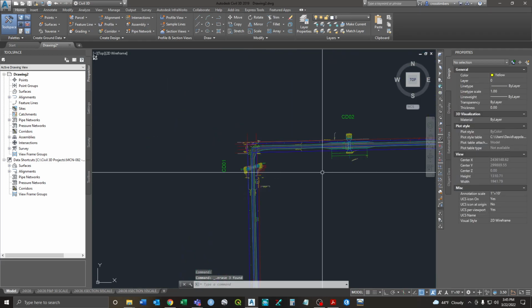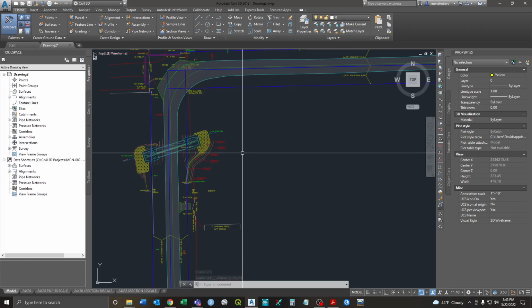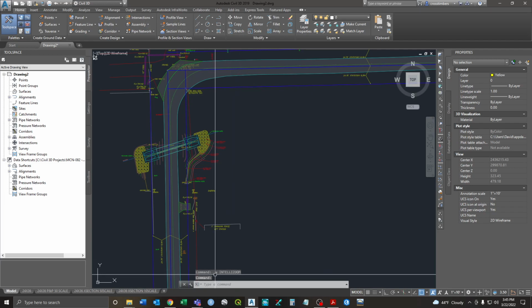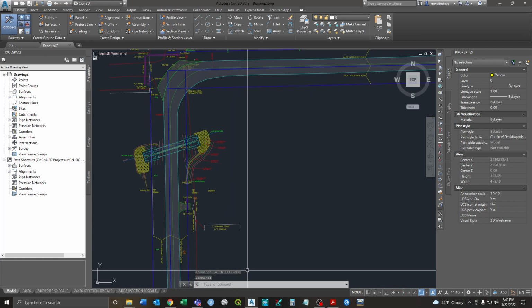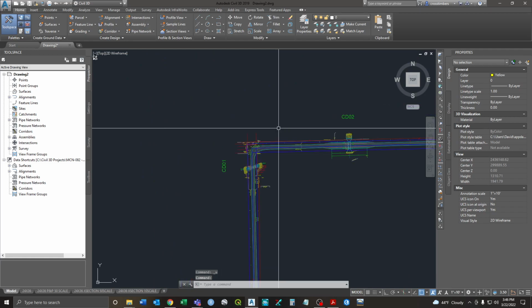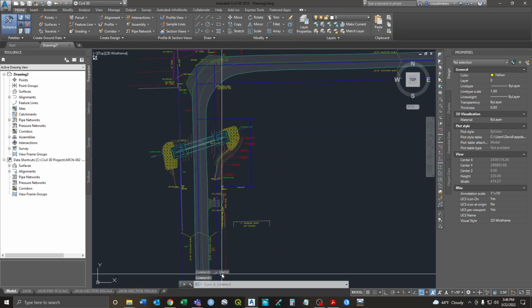And let's just say I zoomed out and I panned over. I'm like, oh crap, I zoom back in. I need that again. So if I hit Control Z, nothing happened. Hit Control Z. Now watch down here. See what it says? Command undo zoom. And you have to keep hitting it. Now it's back. So it says undo the erase.